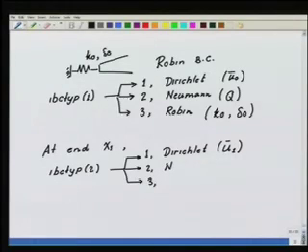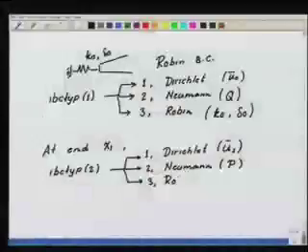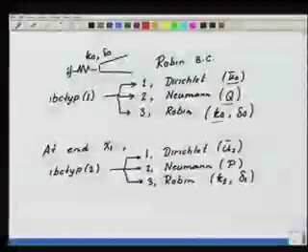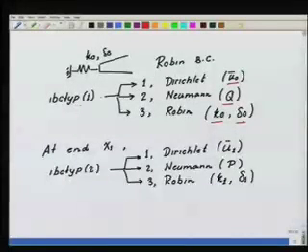If it is Neumann, then it is the end tensile load P, and if it is Robin, then we have to give the end spring constant K1 and the end compression delta 1. So all this data has to be inputted. The boundary condition type has to be specified at each of the ends, and accordingly these data have to be inputted.